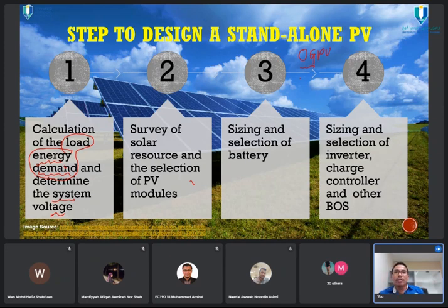So they always say, I want to use the air conditioner for 24 hours, but my budget is only 200 Ah of storage capacity. That's nonsense, because it's not enough.